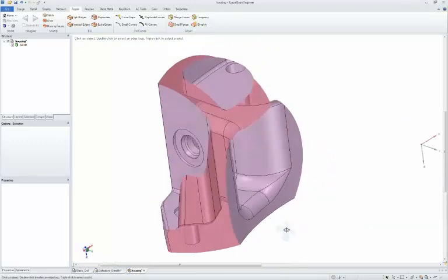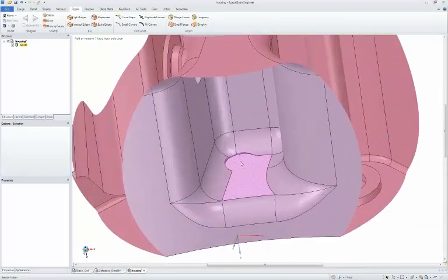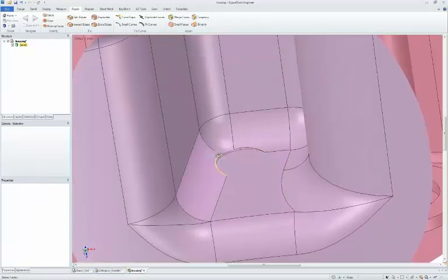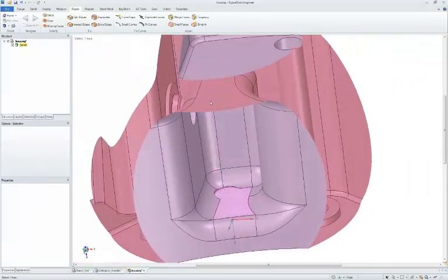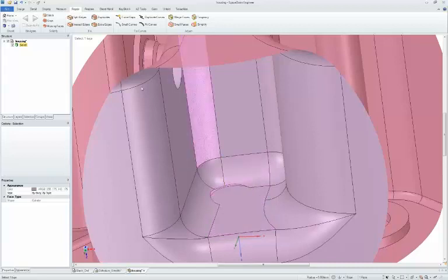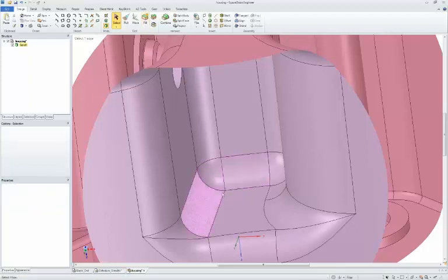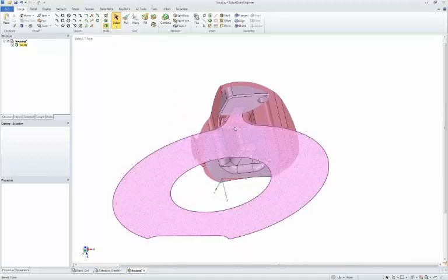So you can see inside of the part of the model what's going on. It looks like someone made a sketch or a circle. This might have been one of the holes on the upper side of the part that they forgot, and now it's cut away. This is a small sliver face that comes together, and that's something I might just want to fill in. Bring it back to the rounds that are there. I won't have to worry about that when meshing.